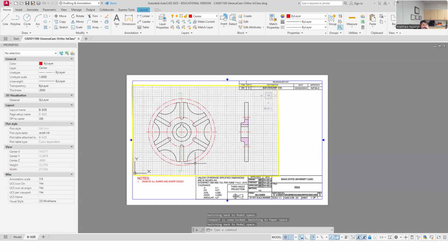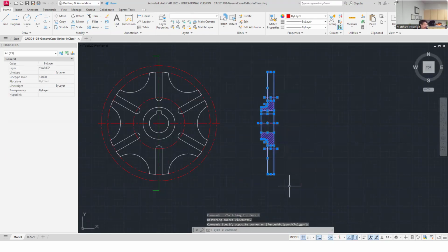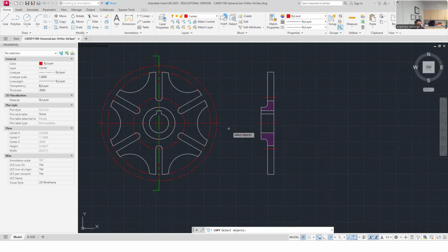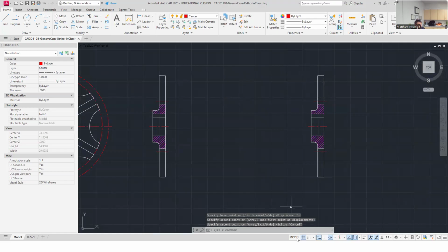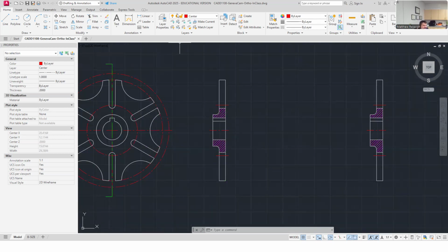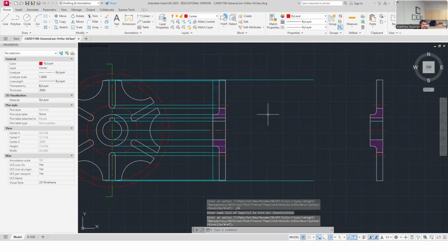Here it might be about right. It worked out for me here. If it doesn't work for you, or however far you place them, or if you put it too close, then we'll just make a new viewport. Of course, if I make things too close before I even dimension it, I'll probably mass select this thing and make a copy. If you ended up putting this too close to your object to dimension, because you will have a few dimensions out here, then make a copy of this thing and pull it out away, to where you can get a viewport that's nice and clean around it without anything interfering, and you can start to dimension to that viewport, right? I don't move these away. I like to leave them. I like to make copies like this, because when I've laid stuff out, I always want to know what I referenced when I laid it out.